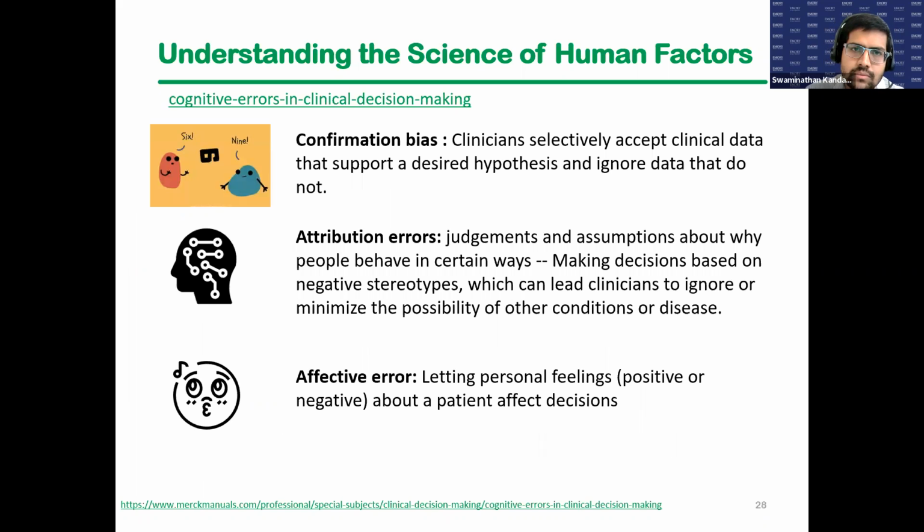There's confirmation bias, which is when you accept data that supports your hypothesis and ignore data that doesn't. Confirmation bias happens often for us when we try to do cross-checking with people. And that is why it's important, let's say, if you are designing a process that has dual checkoff, to make sure that they are independent. So there are lots of little things that may change how we perform an activity, but knowing some of these biases will allow us to put safeguards around how we do them.